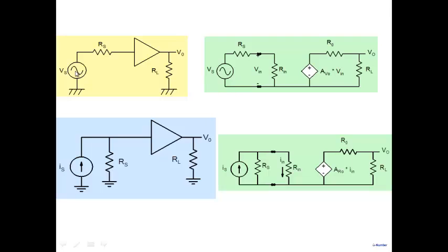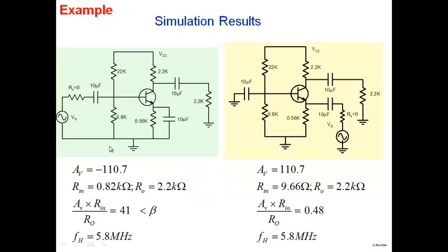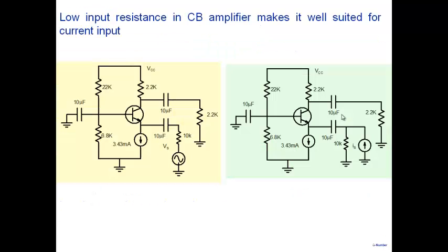If I had a current source input, then I could take my common base amplifier and really use it. Because current source input, remember, will come with Rs or what? If it's a very good current source, Rs will be how much? Very large. Which means, if you take your common base, very large Rs here, so what we are saying is the following. Here, look at this common base amplifier, driven with current source. And Rs is very large. Now maybe I have an amplifier which is useful, right?